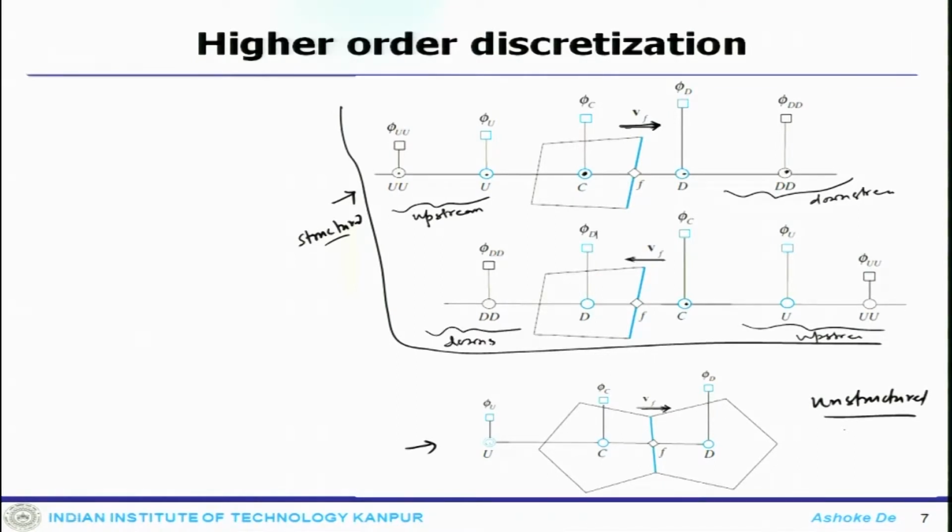So, it just changes the direction depending on the flow velocity direction. This is very useful information and we came across it once we started deriving the discretized equation for the convective term, because this problem was not present for the diffusion term, as there is no convection associated with it.